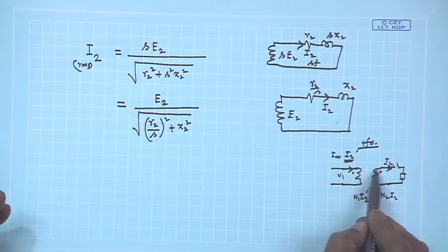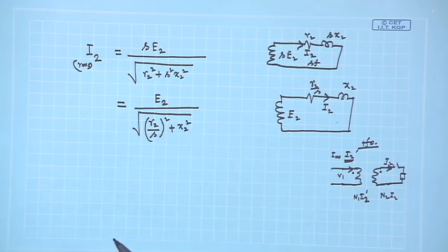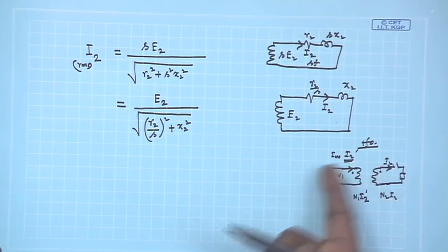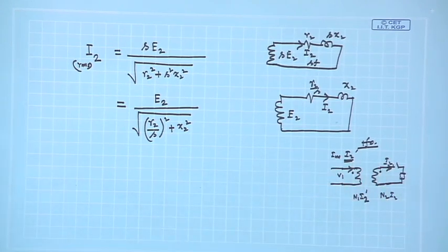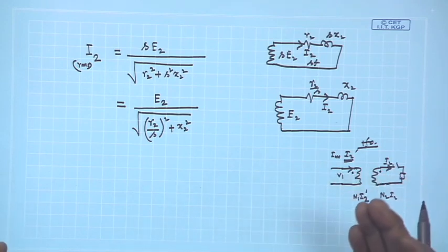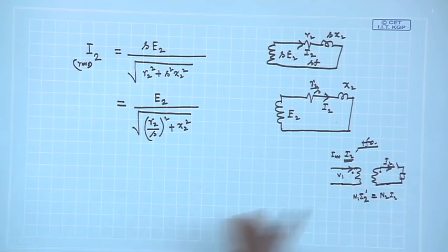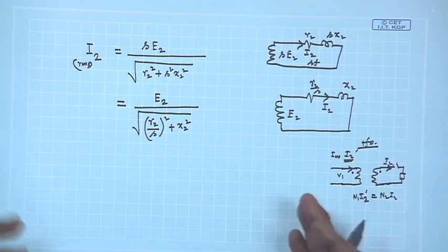From the dot it delivers, from the dot it takes current, such that the total MMF existing in this circuit is once again N1 into Im, the magnetizing current, and flux remains constant, and everything is now nicely satisfied, that is KVL is satisfied, flux has not changed, and your MMF balance also takes place. Any extra current you draw, things will be that.